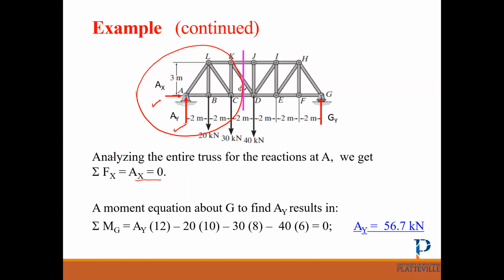If you get the moment about G, remember, anytime you're finding the reaction, you shouldn't cut the truss. Anytime you find the reaction, you consider the whole truss with all external load. This is a very tricky part. Remember, all the time for reaction, consider the whole truss.